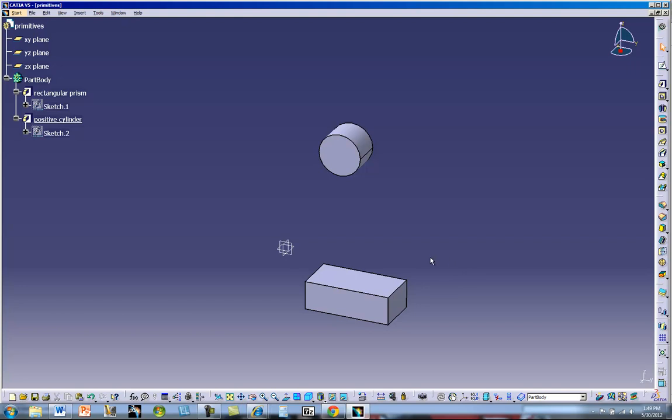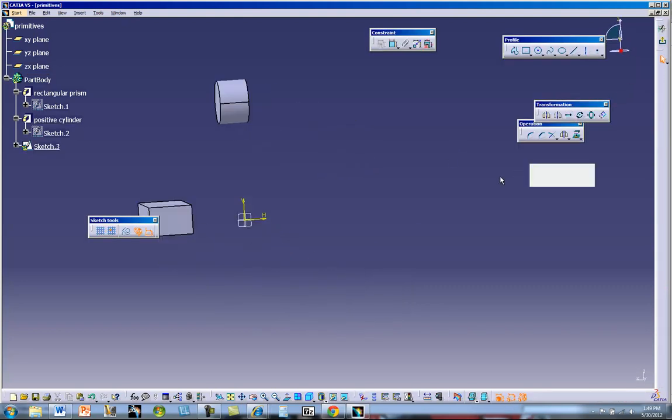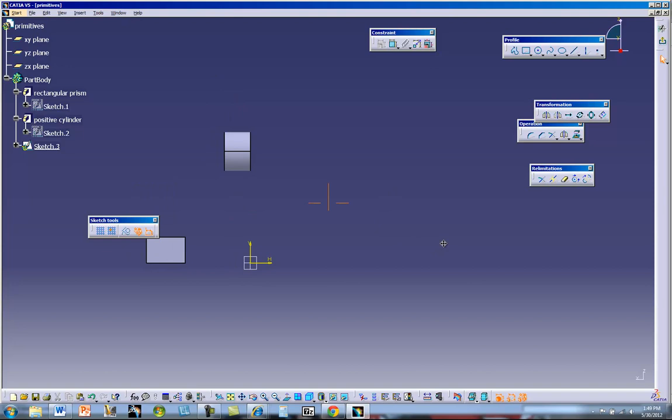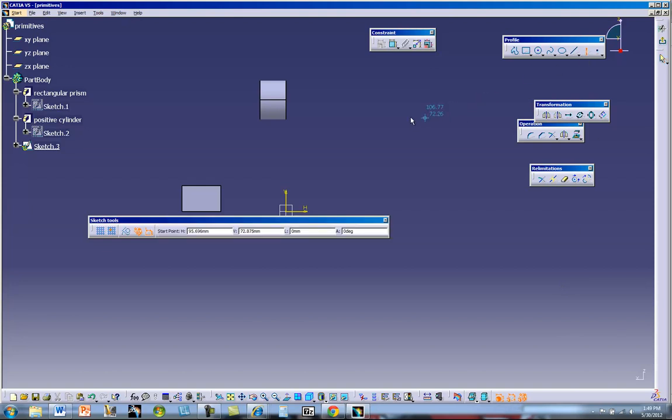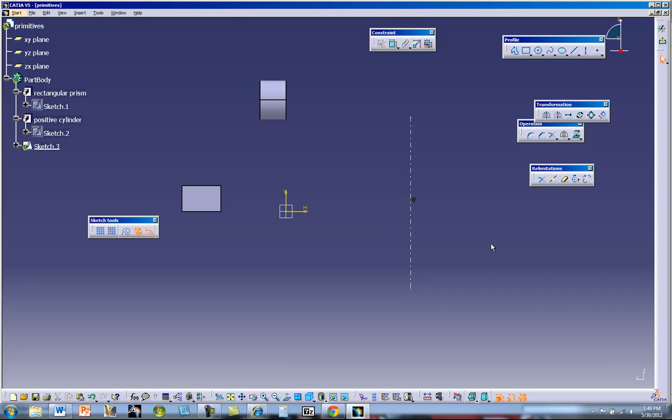Let's build another one here. Let's grab it from this plane right in here. Let's build another sketch. And this time, let's go through and let's make a cone. So a cone needs to be spun around an axis. This is where you want to bring the axis. Command here, grab this thing here. Now again, if you get close to where that's blue, it automatically puts the horizontal constraint on there.